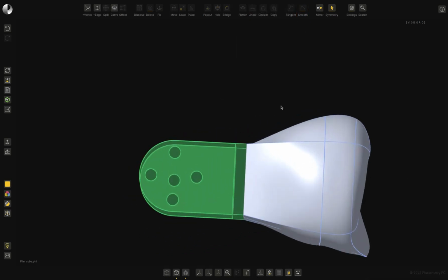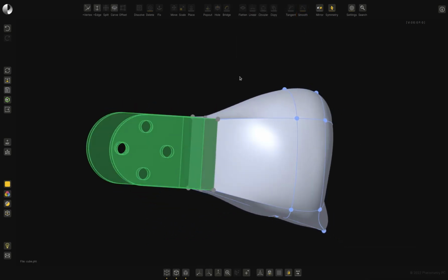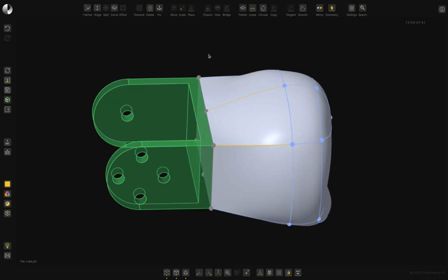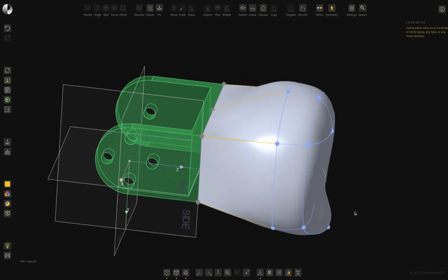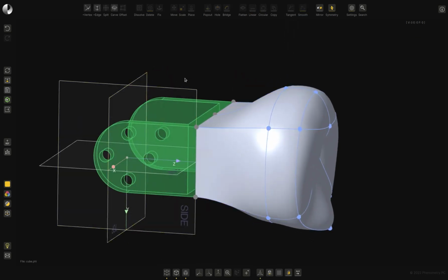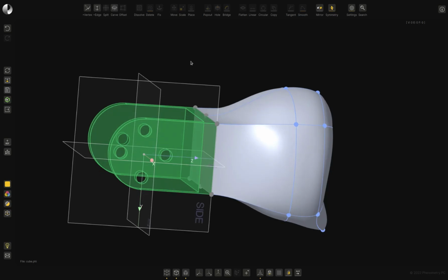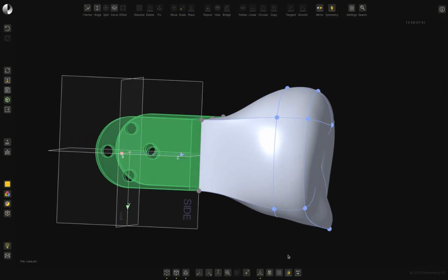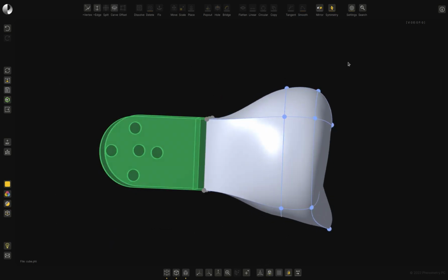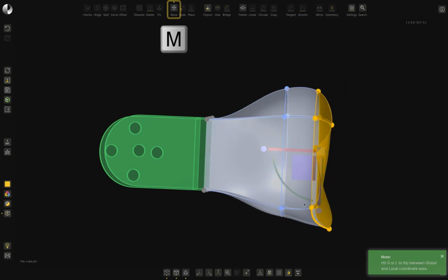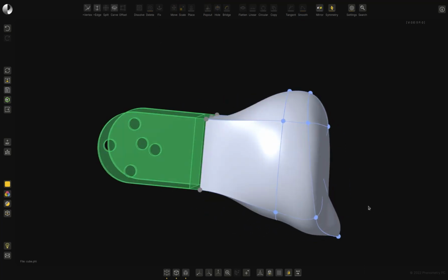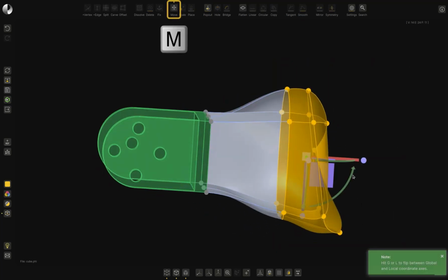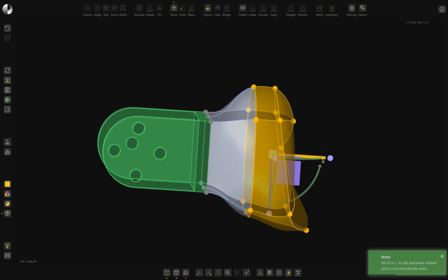And now we are going to make sure that the head comes smoothly out of the plate. So we select all of these edges and then click this icon, which will make them perpendicular to this plane I designate. Or we would have also designated this back face for that matter. I will now select the facade of the inchworm, slightly rotate it and scale it. And then take all of these and move them to the back to reduce the length of the head.